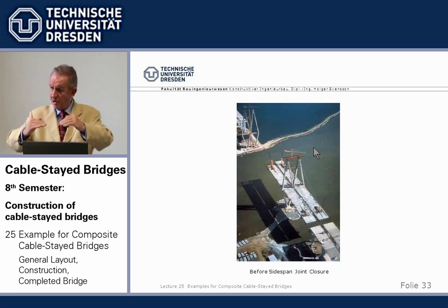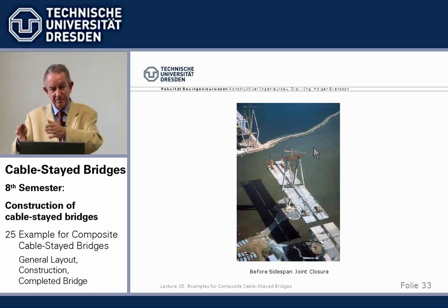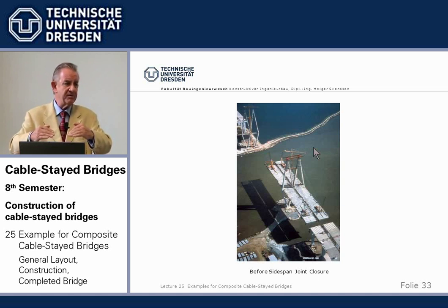the two beams are more stable than any single beam, which has to do that there is some energy transfer from the forward to the backward beam, which disseminates energy, and so it was aerodynamically safer to build the two, although unconnected beams, than to build one single, and the hurricane was a problem there. In addition, the contractor said, well, that helps, makes material transportation easier and all that. That's why the two beams were built in parallel.